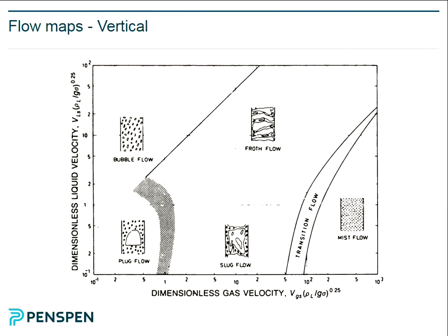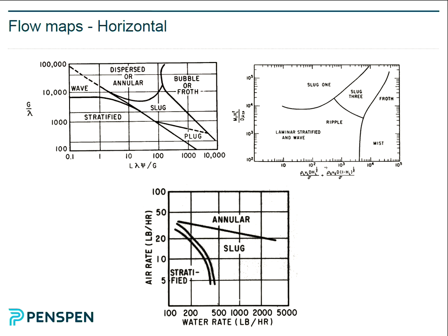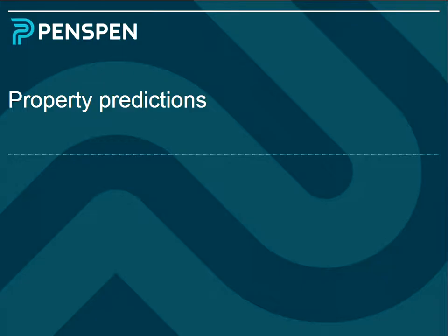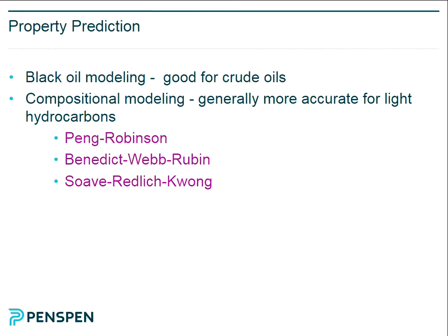These are typical black oil models. Phase equilibria, that's how much is present of gas and liquid at any one time. So Lasater, Standing, and Glasø phase equilibria equations. Oil density, Vasquez. Gas density, Standing-Katz, Wichert-Aziz. Oil viscosity, Beggs-Robinson, Beal. Beggs-Robinson for dead oil. Beal's is based on a logarithm with two different temperatures, two different pressures. And then gas viscosity, Lee, and surface tension, Baker-Swerdloff, basically. That should be highlighted.